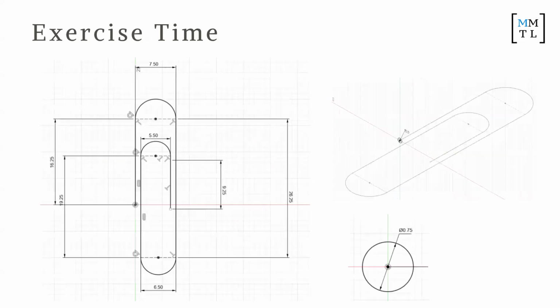So we'll jump right in. Best way to learn it is to just do it. So to recreate this, we're gonna make a paperclip, very simple. So everyone's on a new design. So sketch this out, and you can have a look at the top right image. You can see that you got to do two different planes. So you got to do XY plane, and then the ZX plane. So firstly, draw the outline of the paperclip, and then later on, draw the circle that is the actual paperclip.